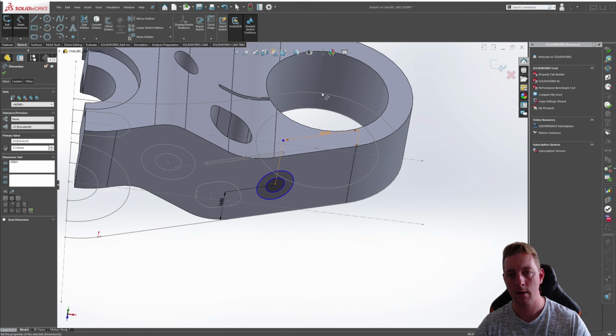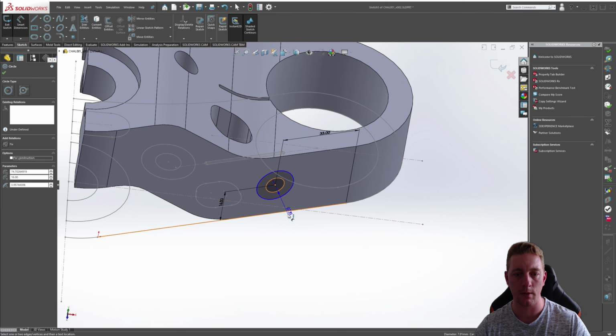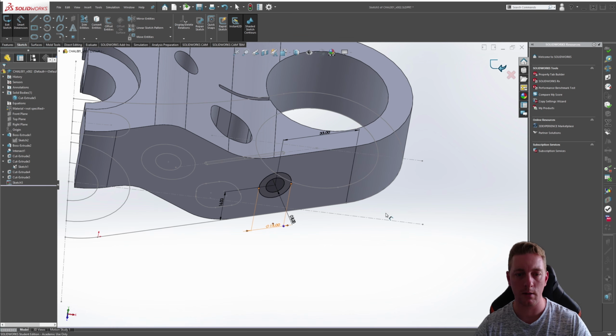That's where, if you were to draw a line perpendicular to this, that's exactly where it is, because that circled edge is tangent and it comes around. So it is perpendicular. I know that's where the 33 is dimensioned from. We also need to add two circular dimensions, which are 14 and 8. So this one is 8, this one is 14, and then close.